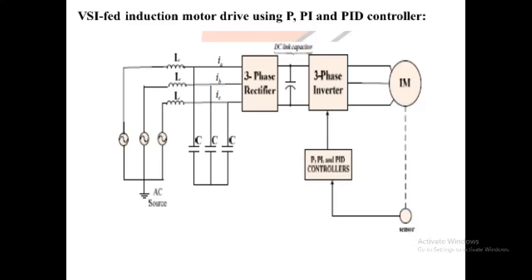In general, the principle of operating a three-phase induction motor indicates that the speed of the motor is directly related to the frequency of the supply. This fact has made the inverter fed induction motor a very common configuration in the majority of industrial applications.